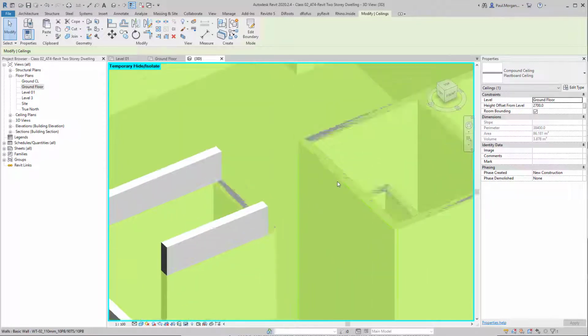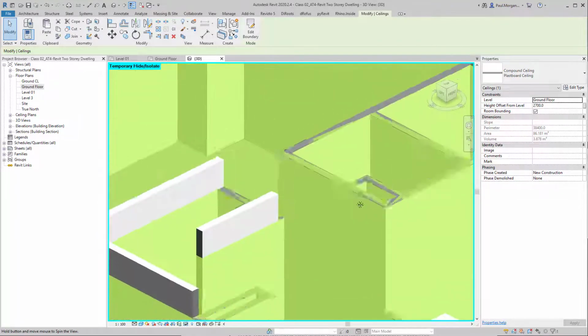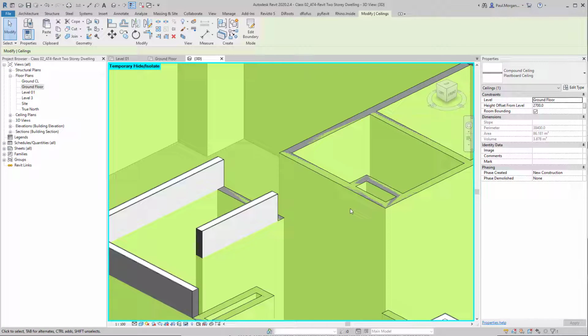you're including everything that's sitting above the studs, and you can see it graphically freaking out because there's two surfaces in the same place. And you may think, okay, well, it's a 90mm timber stud with two 10mm plasterboard at the side, so you're talking 110mm wide. Is it really going to make that much of a difference? Well, it will if you have, like, 100, 200 linear meters of that width. If you had, say, 90 linear meters of 110mm wide wall, that's actually 9.9 square meters that you are miscalculating, which is a substantial amount.